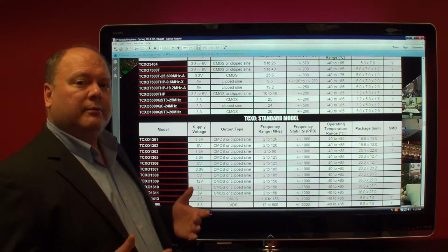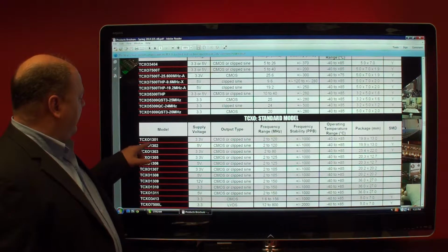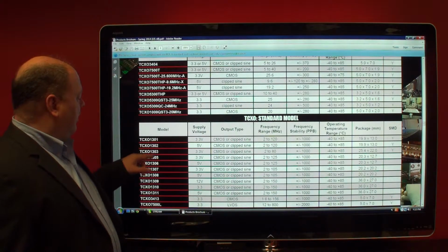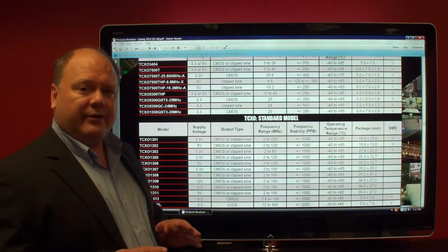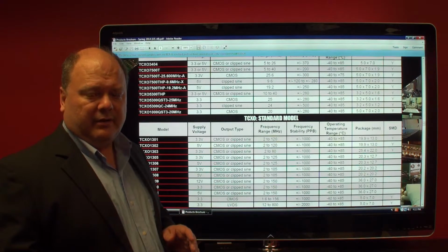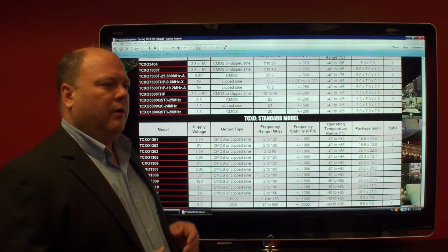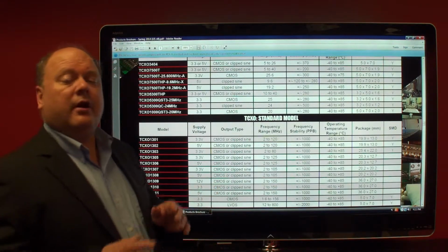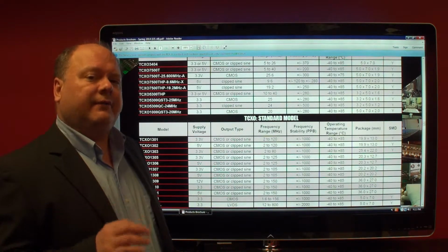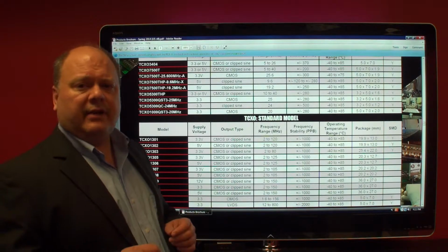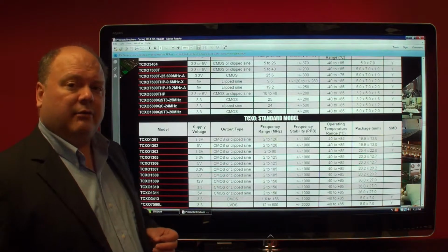As I've said earlier in previous video training, any part number TCXO that has 1301 or 1313, right away you can tell those are general models. They're not custom data sheets. They will offer a frequency range, more than one frequency, or they'll say 5 megahertz to 100 megahertz or 2 megahertz to 80, or they'll have a number of discrete frequencies listed that are considered standard frequencies. That's a general model. You'll have some ordering options related to that general model.